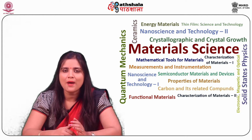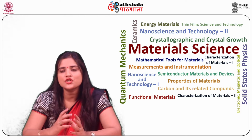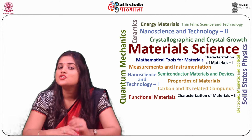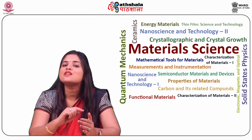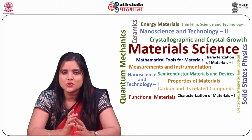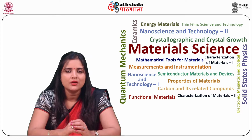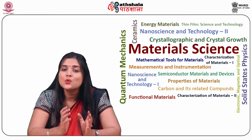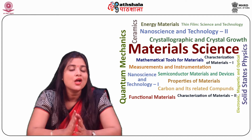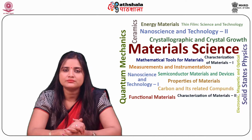The gain of an op-amp can be controlled by introducing a modification in the circuit which involves the use of feedback. That is, output signal is fed back to the input either directly or via another network. This is known as closed loop configuration. For most practical applications, op-amp is operated in closed loop configuration.